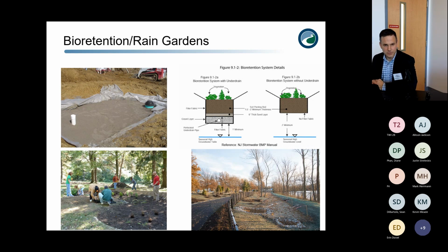Where you'd use an underdrain is if you have poor subsoils, let's say you had clay that can't accept a lot of water, it can't drain it quick enough. So if you don't have an underdrain, you'd end up with a pond that could become mosquito breeding habitat. It would just sit there. And so you need that underdrain to help drain that system after a rainfall event.